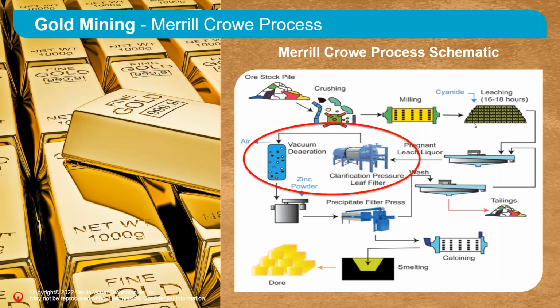After that leaches into it, it is decanted and sent to the Precoat filters to separate the dissolved gold and silver cyanide solution from any of the ore particles. The Precoat filters that are installed here typically remove the suspended ore particles to below 1 ppm. I also want to point out that the next step in the process is to remove any dissolved oxygen in the solution, and we provide vacuum deaerators as well. The vacuum deaerator typically removes dissolved oxygen down to 5 ppb.